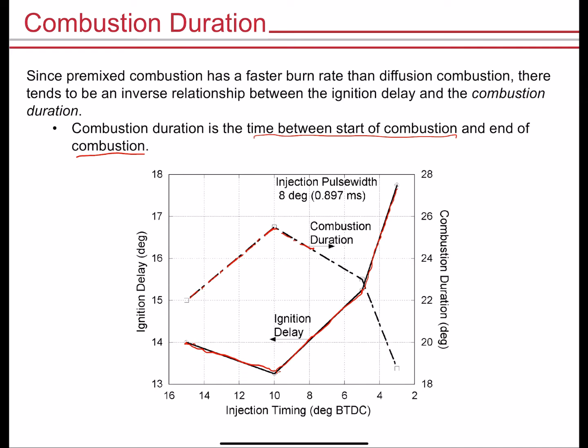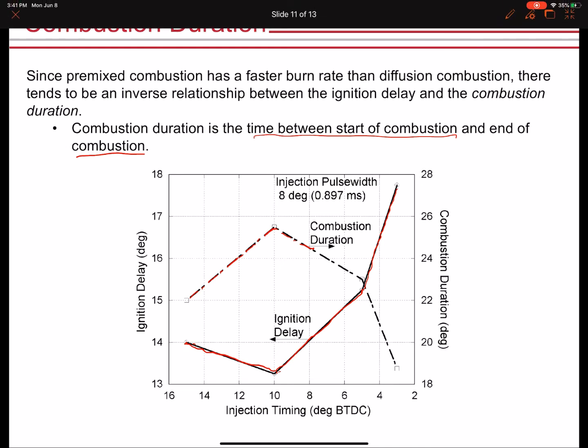Now, of course, what I was studying for my PhD was a novel type of combustion, something which we still study to this day, called premix combustion. The whole idea is to create, remember how we said early on that we want to create as much premix combustion as we possibly can to avoid generating soot. We're not going to get into it in today's lecture, but when we do that by advancing injection timing, we end up introducing the soot-NOx trade-off.